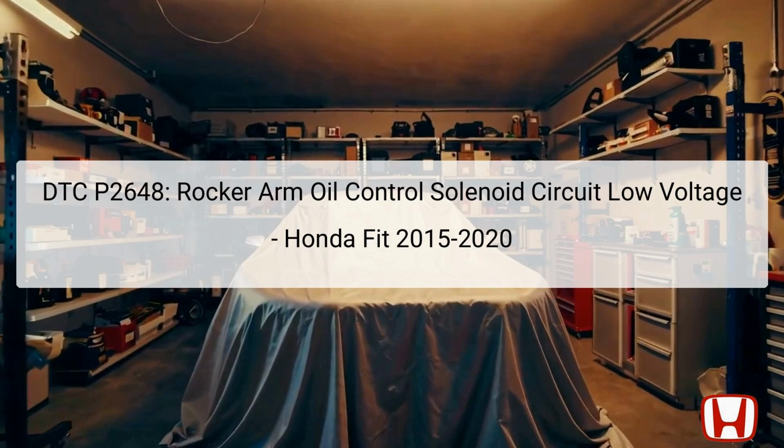The Diagnostic Trouble Code, DTC P2648, indicates a low-voltage condition within the rocker arm oil control solenoid circuit of the 2015 to 2020 Honda Fit. The rocker arm oil control solenoid is a crucial component that regulates oil flow to the rocker arms, which impacts the variable valve timing and lift electronic control (VTEC) system.